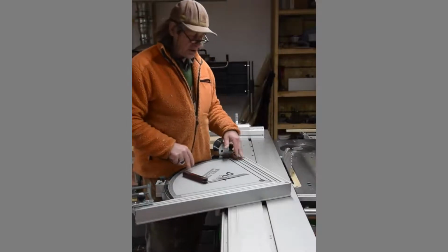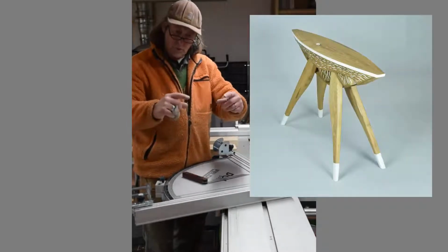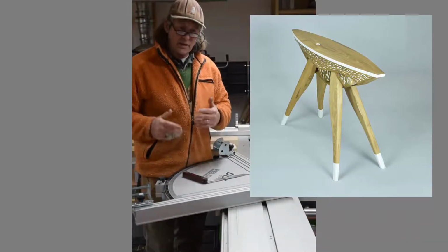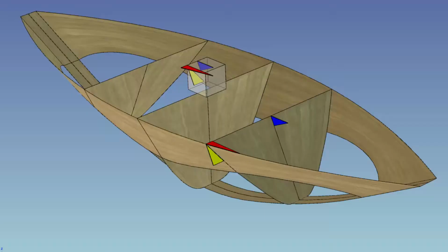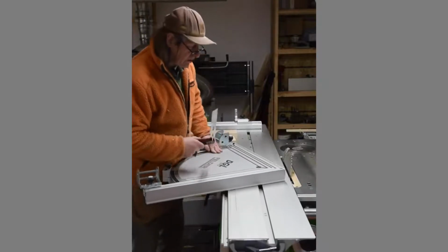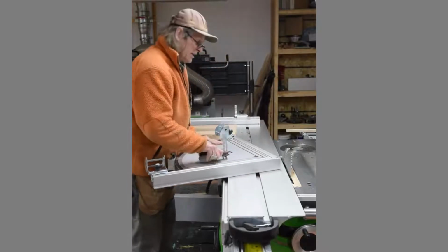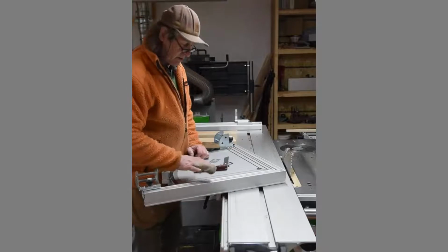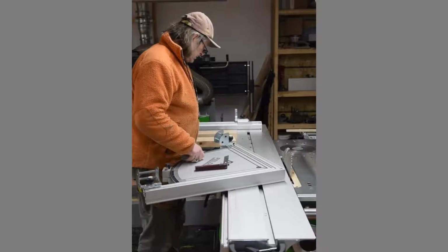To fit the legs snugly under the table, I have to cut them in a compound angle because they are forward or backward and out. To do that, I have to cut the legs on the top and in between in a compound angle, which means a double angle. One angle is 13.5 degrees like this, and the other angle is 23 degrees, and I set that in my miter device.